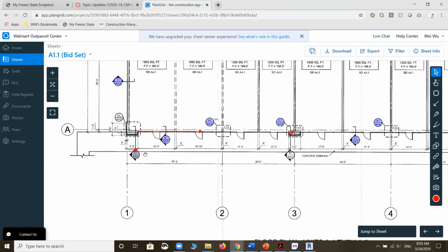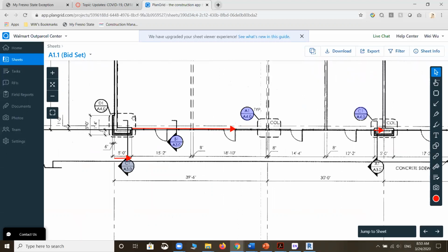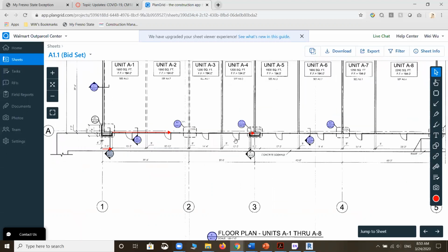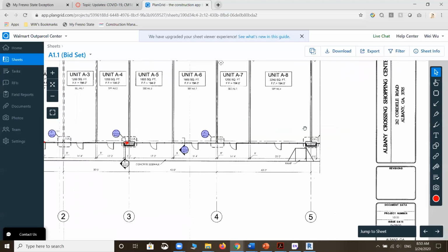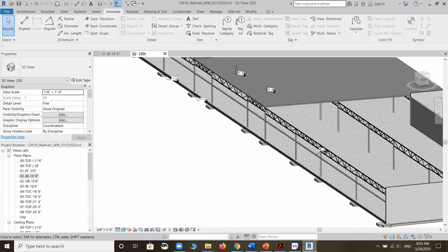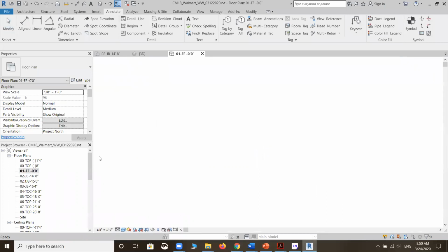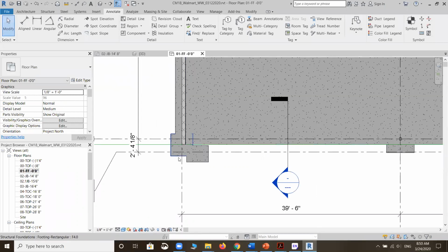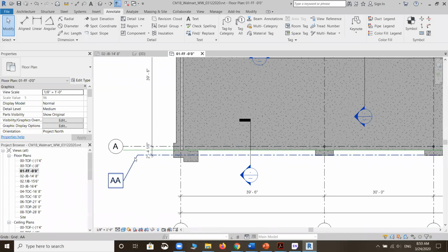Now, what we need to do before we start the actual modeling of the curtain wall system is lay out the curtain wall first. Where does it start? Where does it end for each individual section of curtain wall systems? So what I prefer to do is mark up those starts and ends first. Then we're gonna draw the curtain wall system one by one. So we're gonna rely on something we call the model line tool to create some reference lines for ourselves.